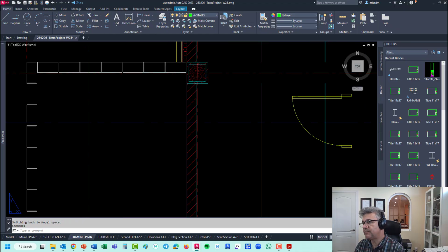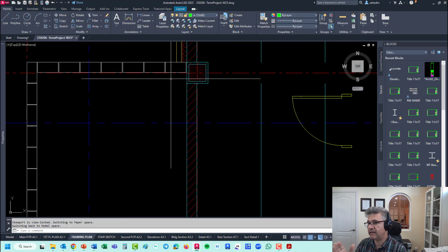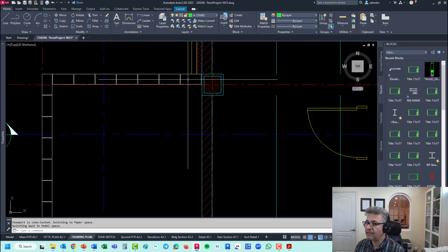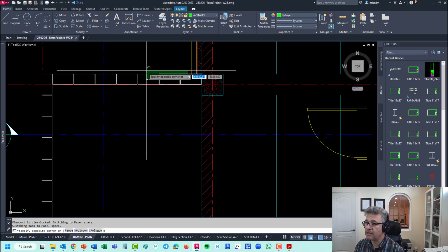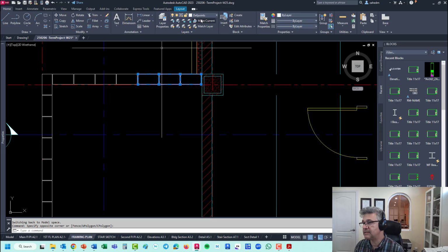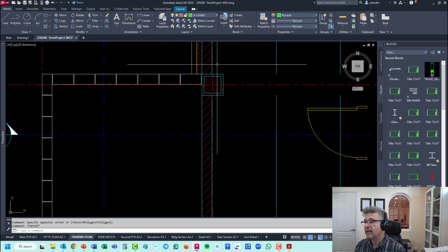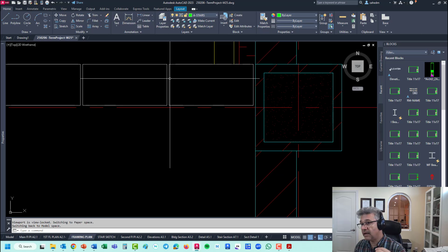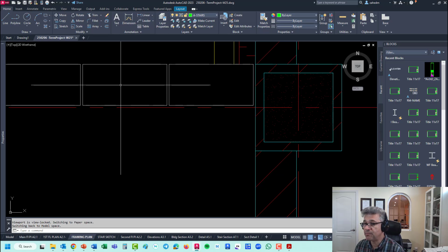Okay, so what is the story of all these blocks? We all know this building is made of concrete block, and we want to add a staircase with the use of concrete block in here. So I created a block. They are all in non-print layers. So as you can see, they are on depth points. These blocks are 390 by 190 and 10 millimeters. It's the mortar between each block.